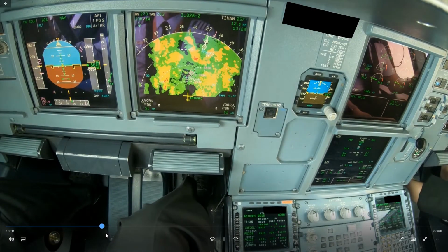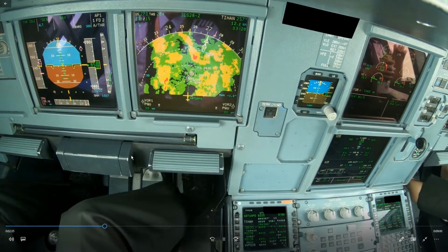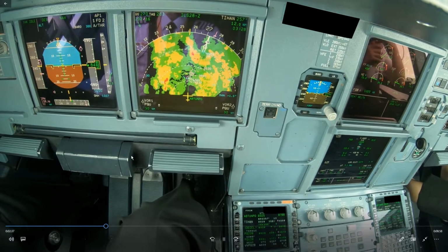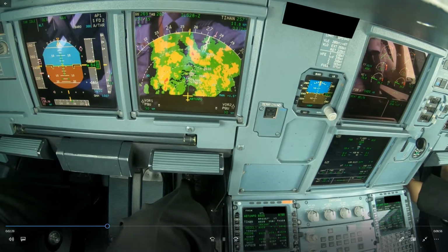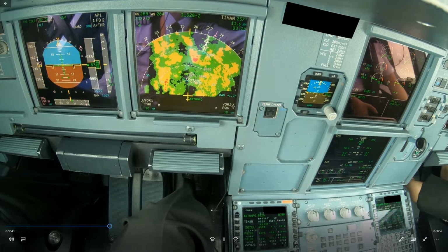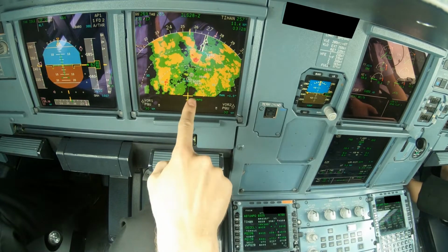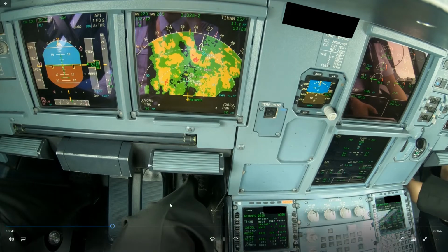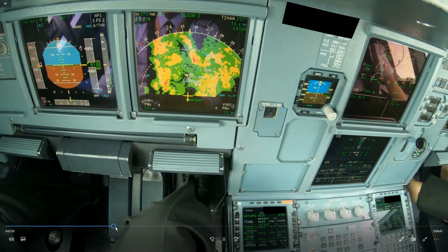So here approaching 30 miles. At 30 miles times 3, that's 9,000 feet. We are doing 250 knots, so we should fly 2,000 feet lower. So we should be at 7,000 feet at 30 miles. Okay, now let's see if we can do that.